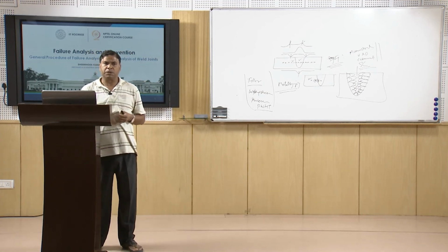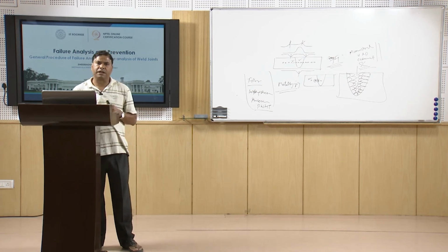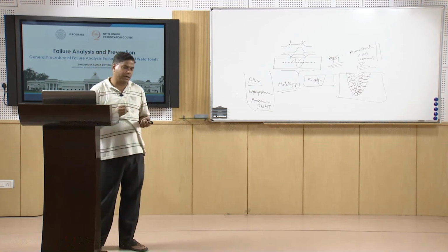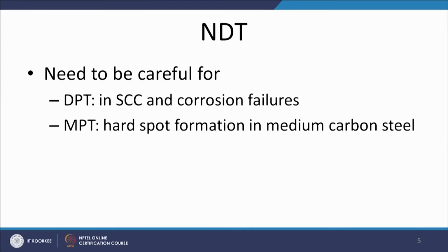In the case of weld joints, we need to carry out NDT with care. NDT is primarily carried out to see the possibility of discontinuities in the weld, and whether they have contributed towards the failure.